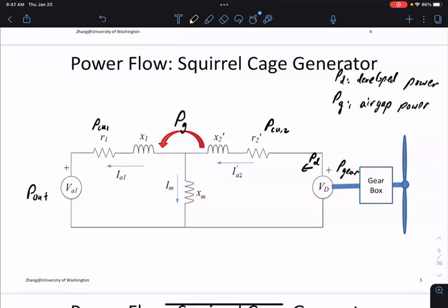There are ways to get rid of IM actually. You either do an equivalent at the primary side, or we just completely ignore IM and not worry about it. Okay? So it's very rare we'll do a calculation explicitly with a shunt reactance in the middle. Of course nowadays, all this is done by computer, so it doesn't matter how complicated it is. But for our problems, we typically get rid of IM in some way. Other questions?